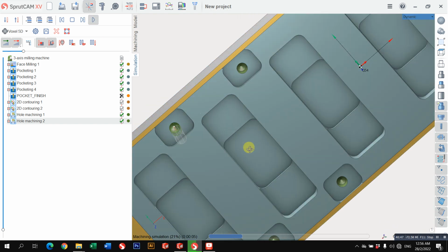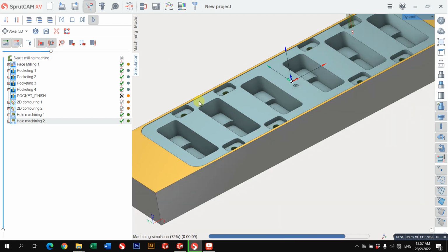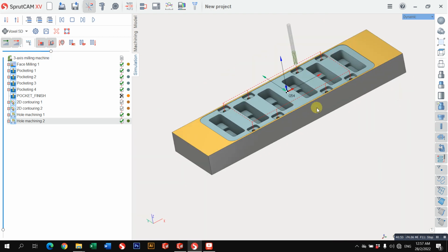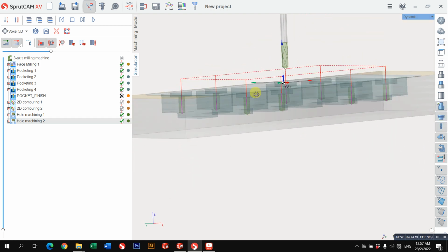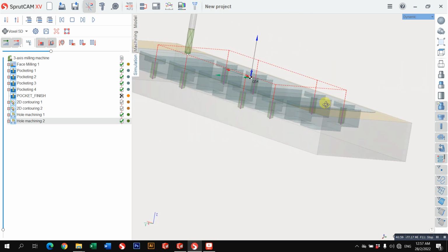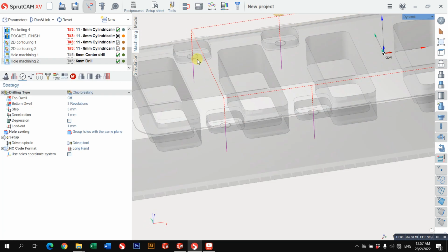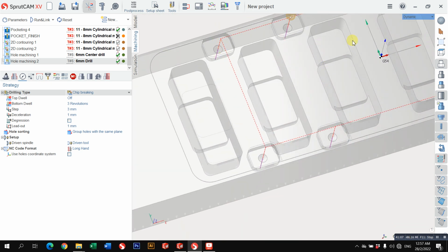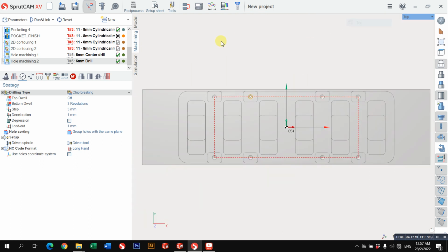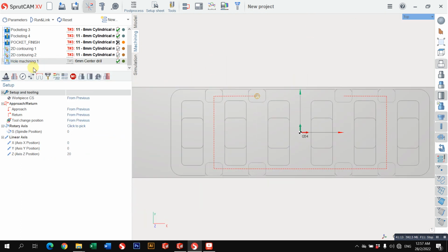Okay, same hole, but this one we want to change the diameter. So here, open this. Now we want to change it to 7, and the drill depth will be -7 to negative. We just want like 10, maybe like 5. So just go to -5.